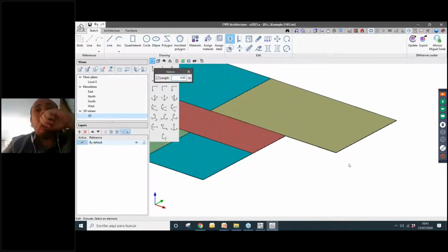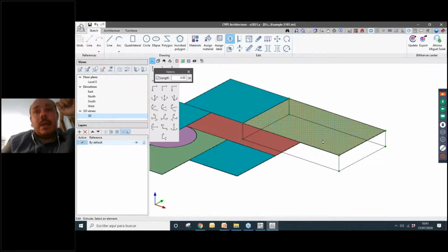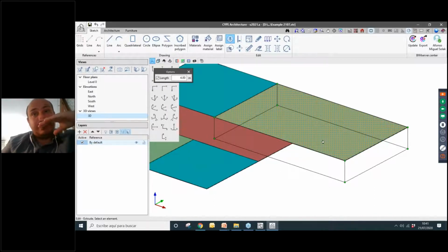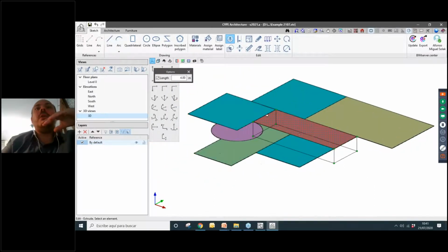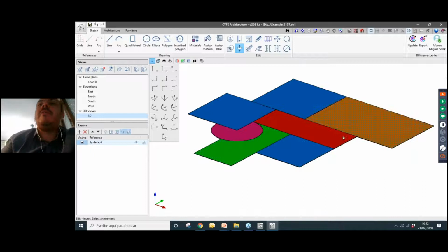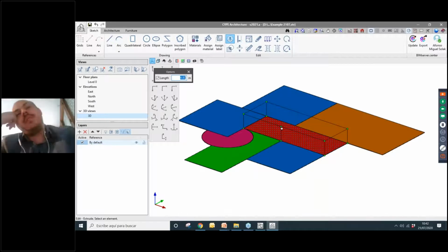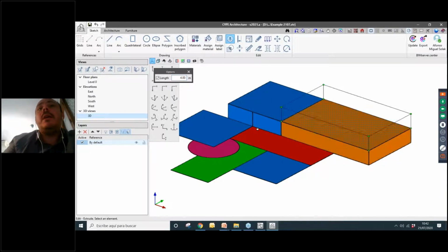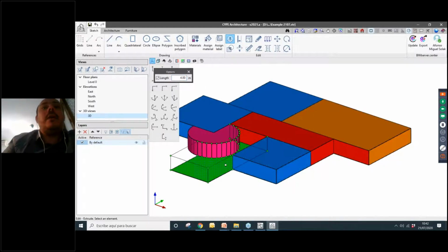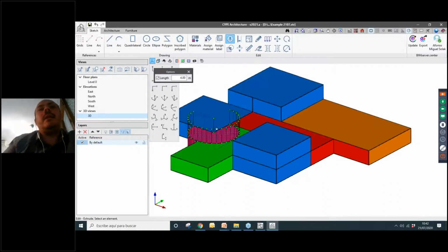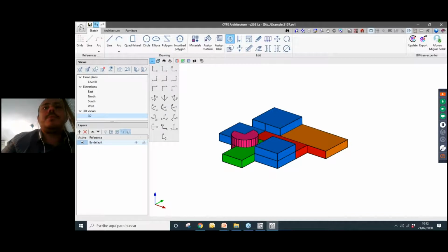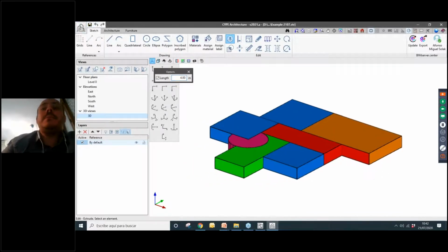As you can see, with this orientation of the surface, the extrusion is going under the surface, okay? In all of these forms that we have here, we can just invert all of them, okay? So let's invert everything here, and then we can use the extrude to the other side. Here you can see the importance of the orientation of the surface again, okay? So we just have to click here, here, here, here, and here. And then we can click again. We have these options, okay? I'll maintain it like that for a while.